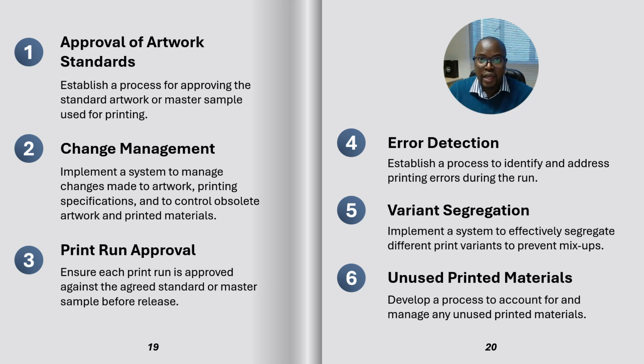And also, it must be following a process. Some of the organizations that are making molded plastic bottles have a limit as to how much rework they can use, because they want to ensure that the quality is not negatively affected. For example, they will say that we do not use rework more than 20%, because in our previous validation studies it has been shown that once we use more than that, it will affect the quality and the stability of our product. So that's something that one can take into account here.